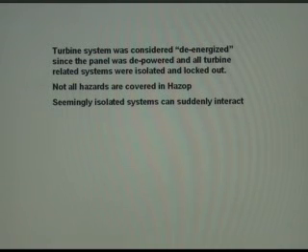There are no optical sensors inside that detect any foreign objects? No. If you tried to measure, the reason is that you've got a horrendous amount of air going into the axial compressor, and if there's any foreign object that's in that gas stream, it's going by so fast that it's almost invisible to the naked eye, so it's going to be almost invisible to any sensor that's trying to pick it up. And even if you had sensors there, by the time it comes into a sensor range, within a quarter of a second, it's into the engine. So you don't have any reaction time to work to it anyway.